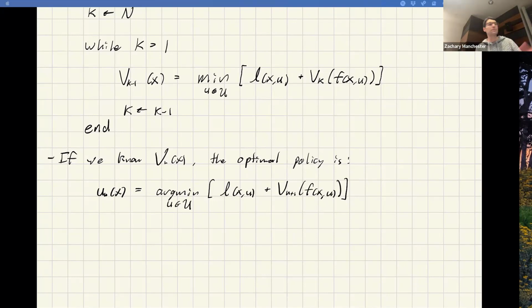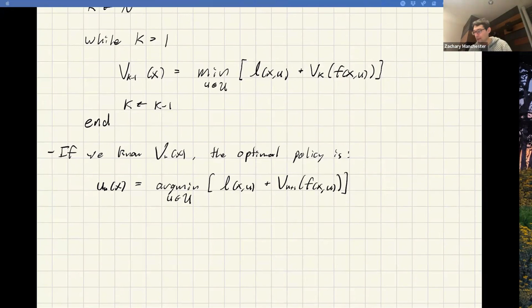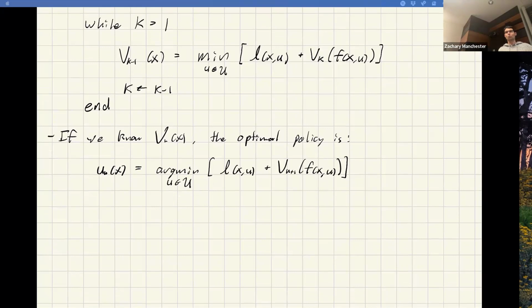Right. Cool. And we did this already. It happens for LQR that I can do that min in closed form and I get u equals minus Kx. Okay, cool. So any questions about this? This is totally general for any nonlinear problem in principle. I can do this and get the whole thing. Yeah. In the LQR case, you end up with your P of k minus 1, and you're just accumulating those. Yeah, I recursively keep going backwards. I get all the Ps and all the Ks in the LQR case, right?